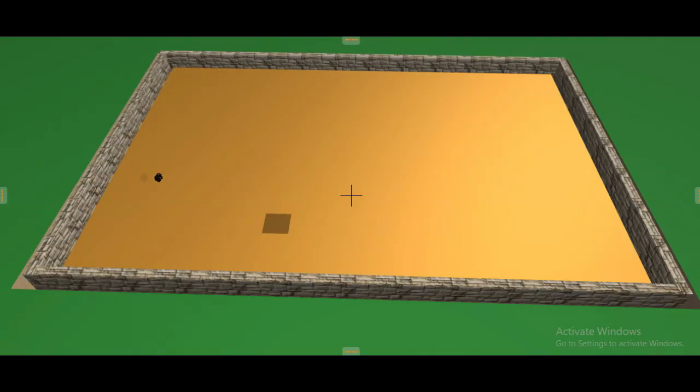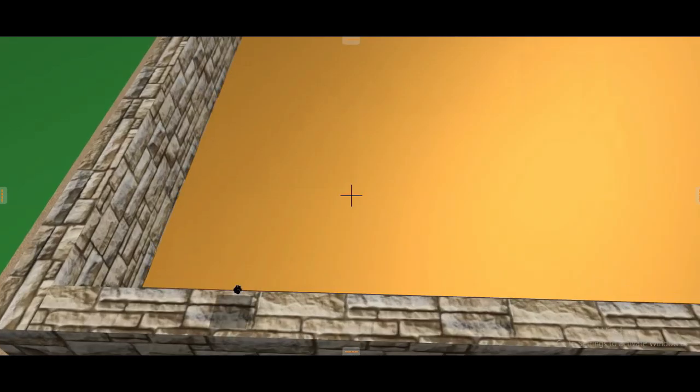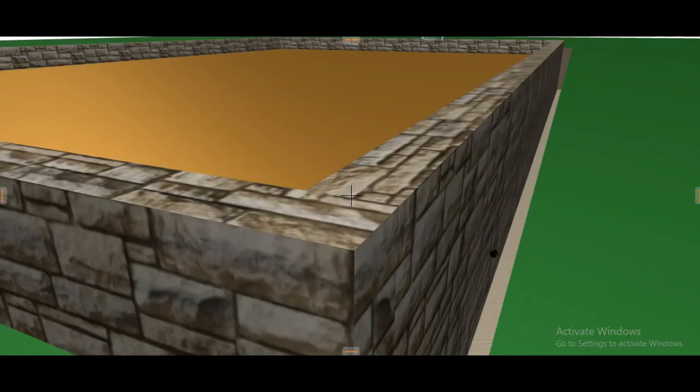So to demonstrate foundation walling, it is this wall. This is the foundation wall, and the mean girth is taken from the center line of this, and all around we are having a mean girth of 39.20. Let me give you a close range. The mean girth I'm talking about, we are taking it at the center of this. So from this edge to this edge, we take it at the center of this. And the depth, that is 1.10 meters from this edge now down to this foundation mass.